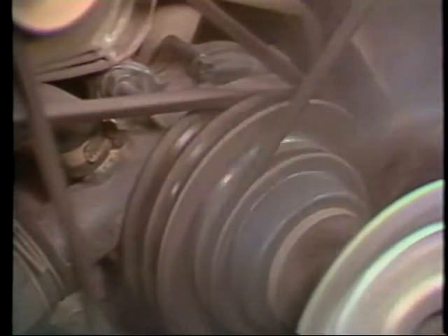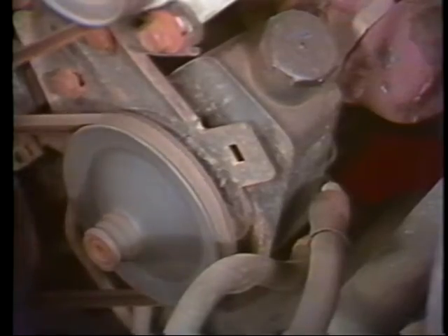Interpreting engine noises is also an important diagnostic procedure. Running noises can be caused by lots of different engine failures, as well as auxiliary component failures. Reaction of failed components to changes in engine operating modes can help us pinpoint the failed components. Auxiliary components such as water pumps, power steering pumps, and alternators can be quickly isolated by belt removal.